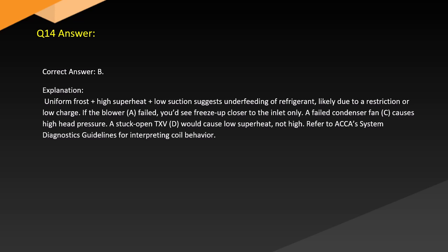If the blower failed (A), you'd see freeze-up closer to the inlet only. A failed condenser fan (C) causes high head pressure. A stuck-open TXV (D) would cause low superheat, not high. Refer to system diagnostics guidelines for interpreting coil behavior.